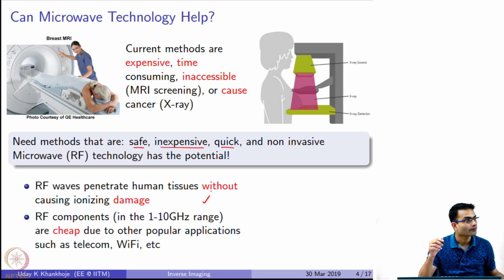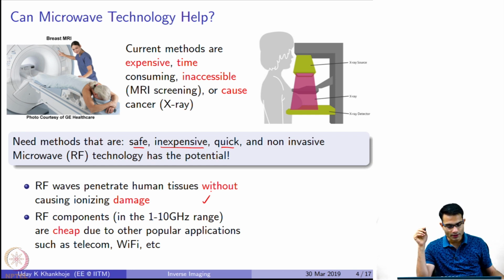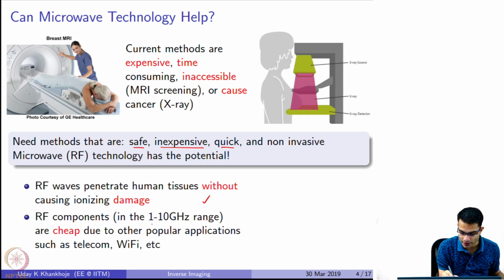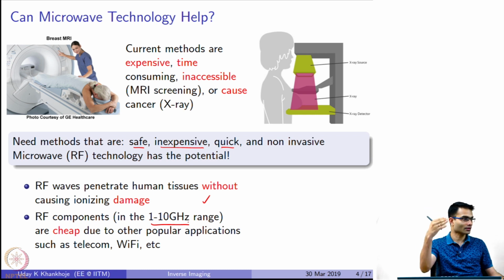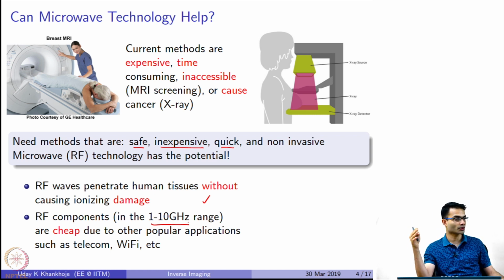So what is the frequency range for imaging applications? Good question. So as I mentioned over here, we keep it roughly in the 1 to 10 gigahertz range, okay? As you go to, well, we'll come to terahertz. Terahertz has other problems. To make a source that can generate terahertz is itself a challenging problem. So terahertz sources are themselves expensive. One of your main goals was to keep it low cost. You don't want to defeat that by having a very expensive source. Your source is expensive, your detector is expensive, all of those things.